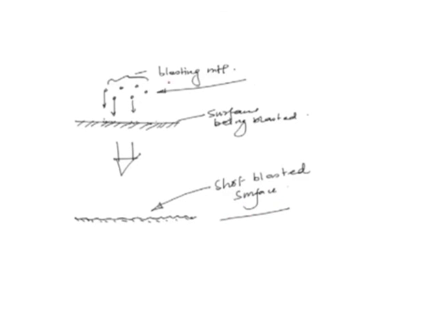These particles are less than 50 micron in diameter, and they can be of alumina, or in some cases cast iron, etc. Now, if these particles are inhaled by any worker, that is certainly not a healthy situation, and this can be avoided by use of robots.